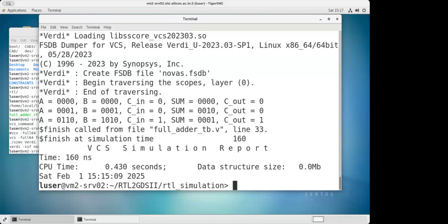That's the reason people came up with another language, which is kind of creating an environment around the design. Around whatever you have written in Verilog, they will write another code which is going to automatically generate these patterns. These are the combinations. So I will automate this part also.